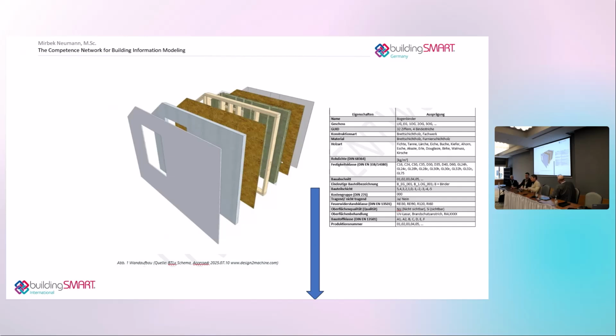And what's interesting, if you go to IFC element assembly, you have trusses, girders, decks, especially deck, if you're building a platform. In that case, not many know that even a classical wall has a really interesting predefined type called elemented wall. And that's what you can see now. That's elemented wall. It's still defined in the BTLX schema, it's a completely different world, but we can cover that. We can address that. We can deliver that.